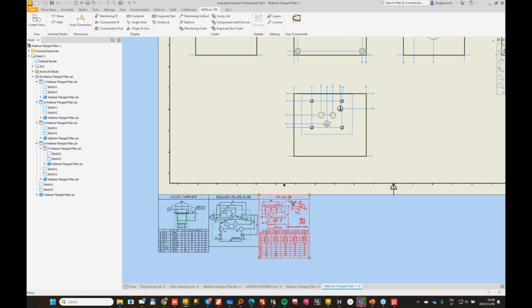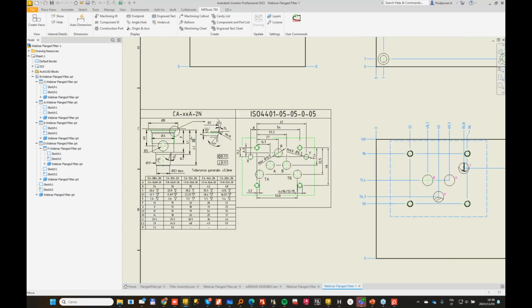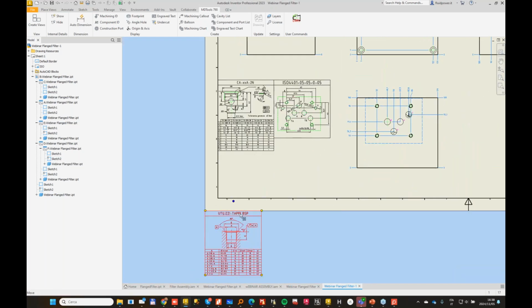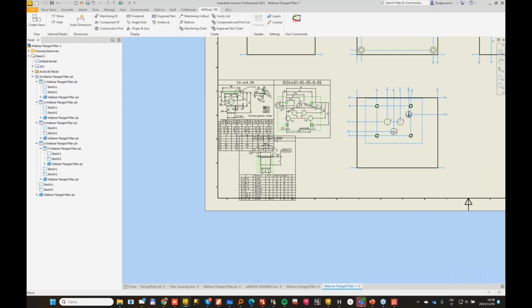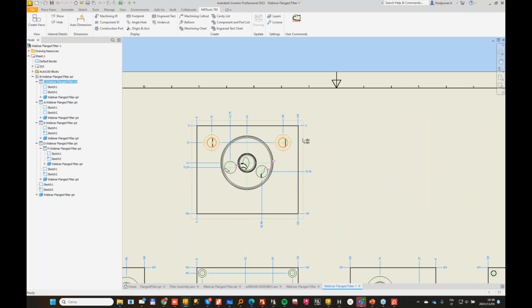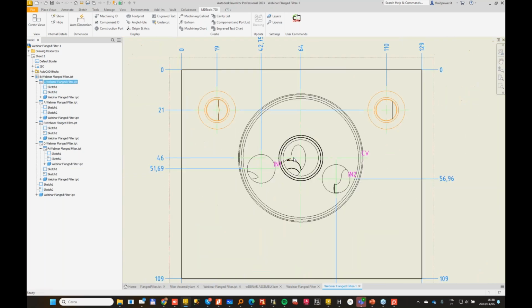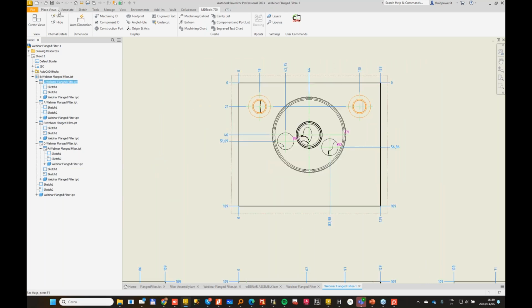So usually I have created cavity blocks describing the most common cavities. In my case, there are SA10-2 cavities and CTOP 3. Then I have a standard table for the BSP ports and plugs. In case of the filter cavity, I think it's worth creating a cross section. So usually I create a custom cavity drawing for all the standard cavities. For this special situation, I normally make a cross section.